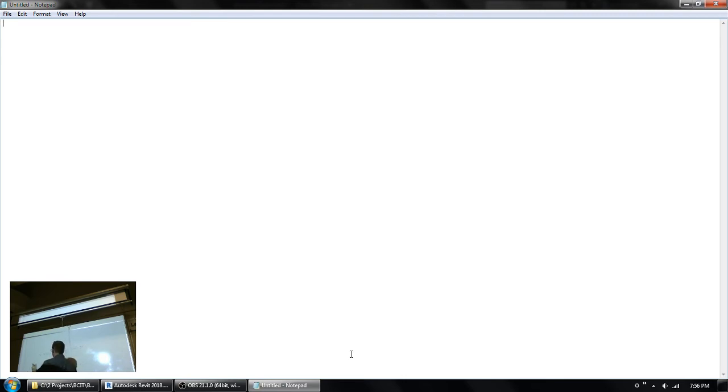And then finally, this open web steel joist is now sitting finally on a W-shaped beam, which carries this whole business. Holy smokes, I'm totally out of scale. So here, we might more like this. Now it'd be a little L angle, a steel angle at the side, and there's your concrete layer on top.